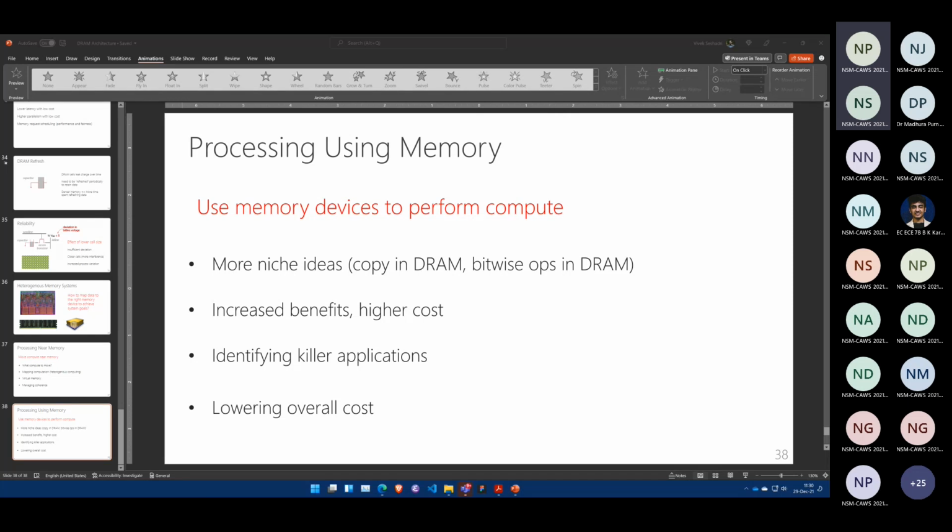Variable retention time is a single cell essentially retaining data for different lengths of time. Let's say you normally observe the cell, it will be retaining data for even 1 second, so you don't need to refresh that cell for even 1 second, but suddenly there'll be a drop, and it'll retain data only for 32 milliseconds. People have not fully understood this phenomenon yet. It's not even understood how we can identify cells that exhibit VRT efficiently, so that we can maybe discard those cells or whatever. But that is something that you may want to look at.